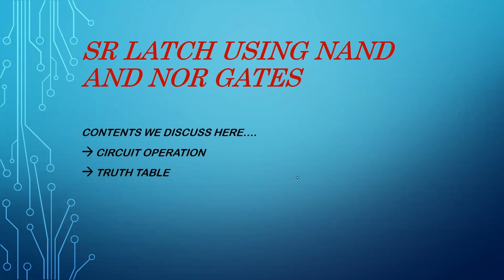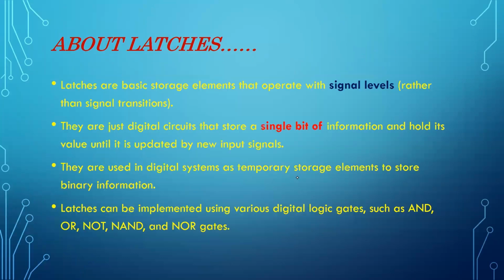So let us see the SR latch using NAND and NOR gates, its circuit operation and its functionality using a truth table. Before going to learn about the SR latch, first we need to know what a latch is. Latches are basic storage elements that operate with signal levels, not with signal transitions.